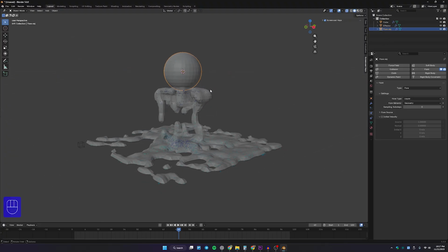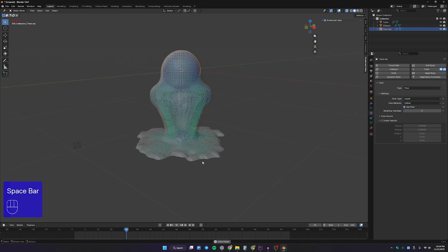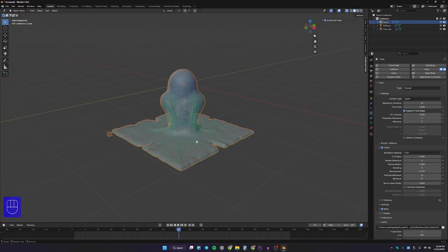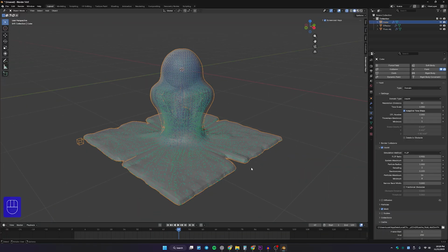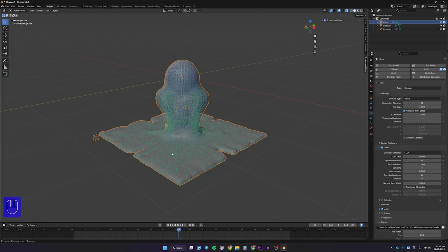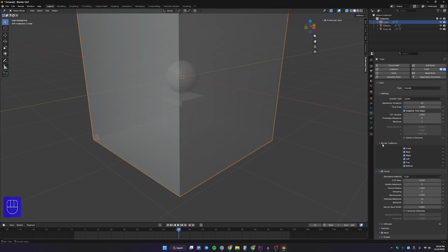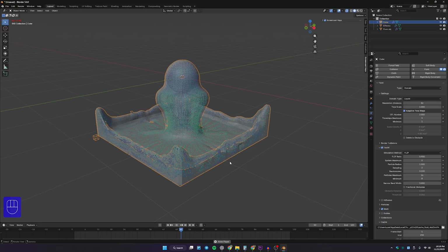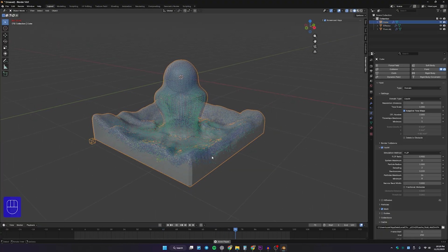So if I turn this flow object back to inflow, if you remember, inflow is always creating your flow continually. Now if you go back, the flow is creating continually. I already turned off my sidewalls. Since that is the case, my particles are being deleted when they hit the sidewalls, disappearing. So I can go here into my settings and border collisions, and I'm going to turn it back on. Now if I play this simulation again, you can see the particle volume is always going up.